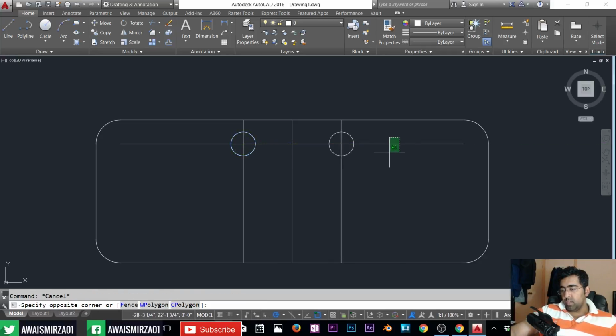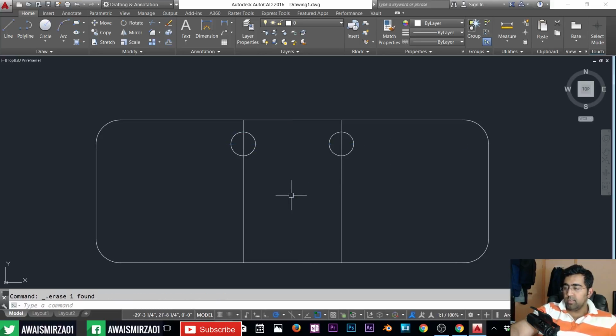Okay, now we can actually get rid of these lines, get rid of this line, and then I need the same kind of distance here. So what I can do is draw a line from this midpoint towards this angle, and now I can give 3 inches. The distance from this line to this line was 3 inches, right? That's why we selected that node.